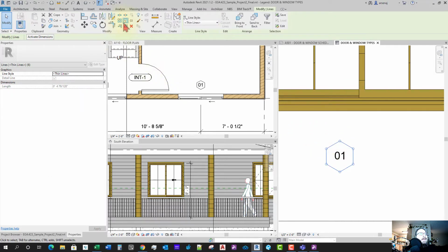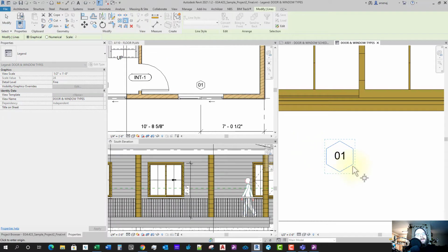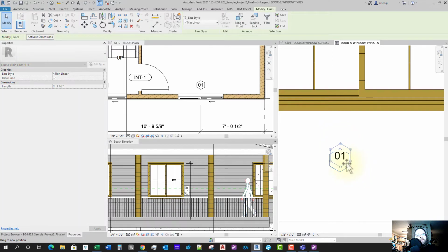And then I'm going to just scale it down a little bit. Scale is found under the Modify tab. And then here next to the mirror, trim, and it's right above the trim extend multiple. And I'm going to do graphical scale, which means I'm going to pick one point, grab another, and just resize it.